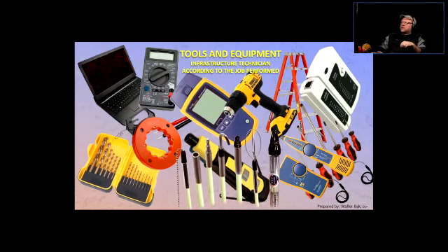And then in some specialty cases, when you're going to do a lot of heavier drilling, like for example, stuff that we're going to mention later on in the second part of this lecture, like drop-in anchors, okay, those require, in order to mount some raceways in this concrete ceiling, you're going to not only have to use the powered type of drill, a hammer drill, but it's going to be a little bit heavier duty hammer drill, and sometimes you can rent those, okay, because the price goes up. And sometimes if you do a lot of work like that, you might want to buy your own.